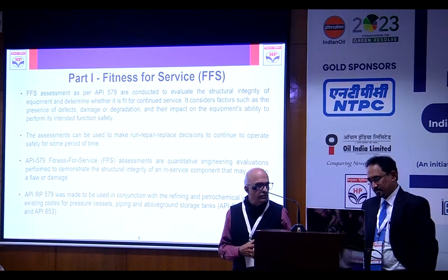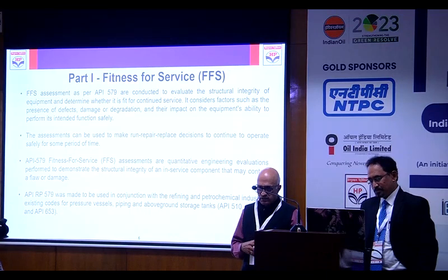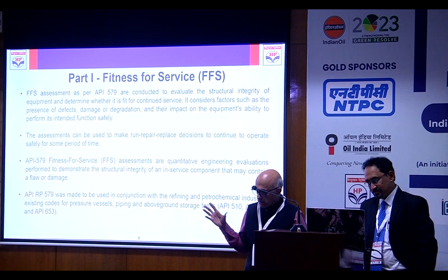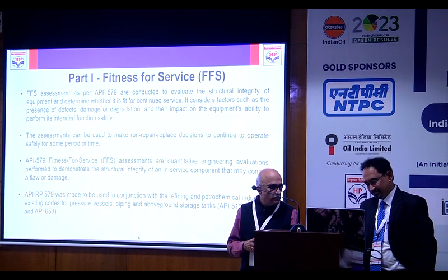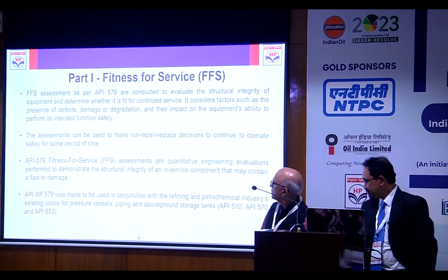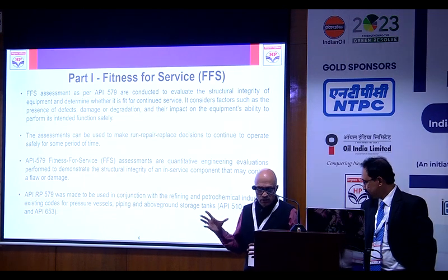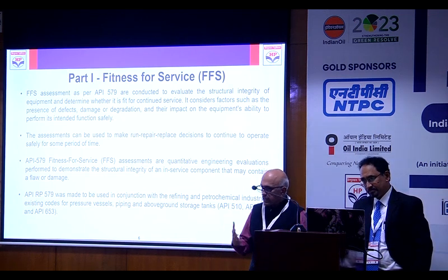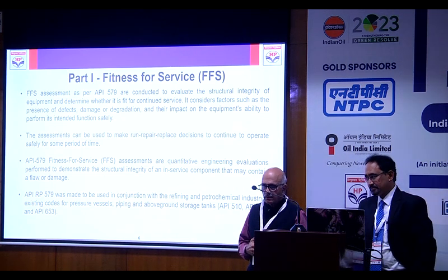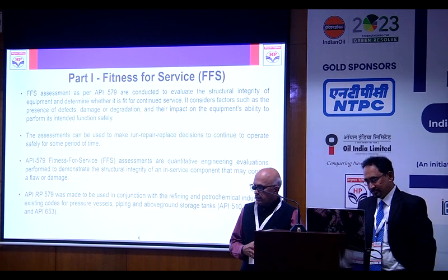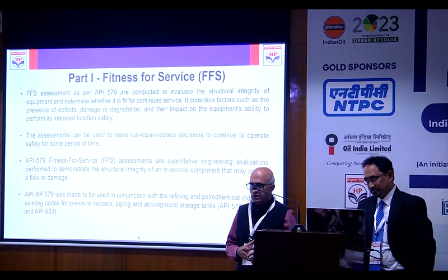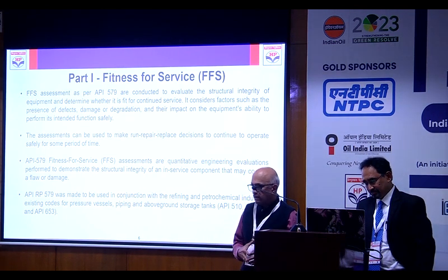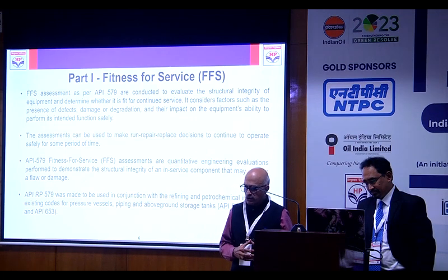So the first part I will be dealing with is FFS, how we use it in the refinery, through a case. I think we had an earlier detailed presentation on FFS from ProSim. They have done an excellent job. So this is a procedure that we follow. API 579 deals with a structured way of how we do FFS. See, there is level 1, level 2, level 3. Level 1 is at plant level, we can handle it. Level 2 and level 3 are more complicated and need expert experience in handling those things. We will be taking those services from outside, but knowing these things is very useful for the owner to take a business call.